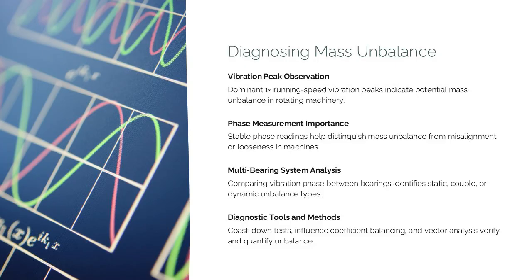Phase measurements are especially critical, as they help differentiate unbalance from misalignment or looseness. In multi-bearing systems, comparing vibration phase between bearings reveals whether the unbalance is static, couple, or dynamic. Correct interpretation ensures proper corrective action without unnecessary maintenance.